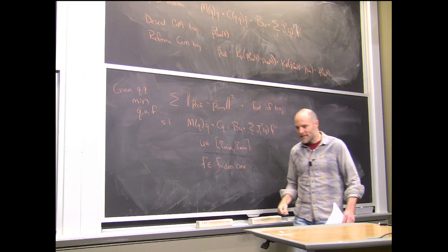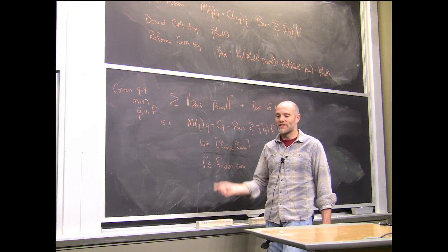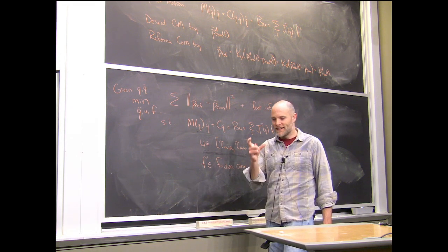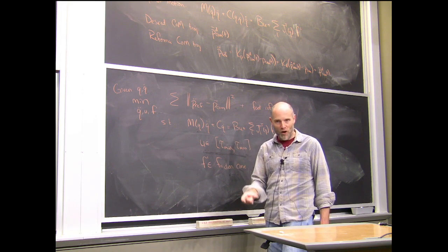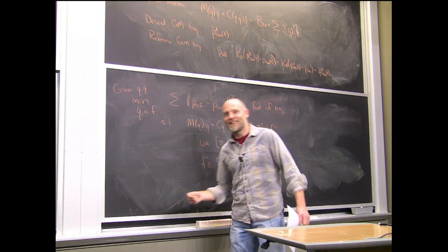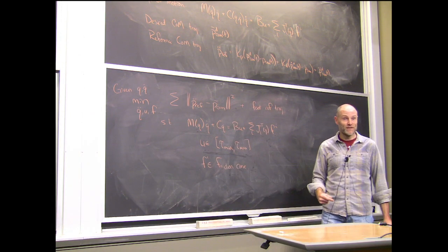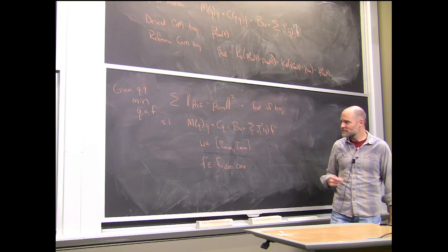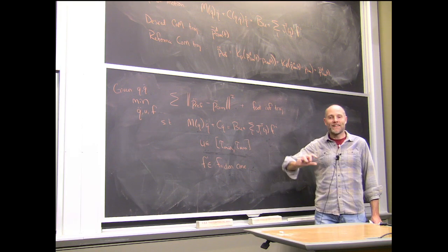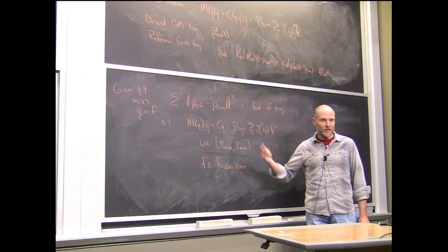that if our FastQP ever failed and we had to stop and call Gurobi, the delay that resulted from calling Gurobi made the robot often fall down, or you could definitely see it have problems. It would jerk or something because the QP solver got slow for a second. But as our QP solver got faster, the simple heuristics also worked better.